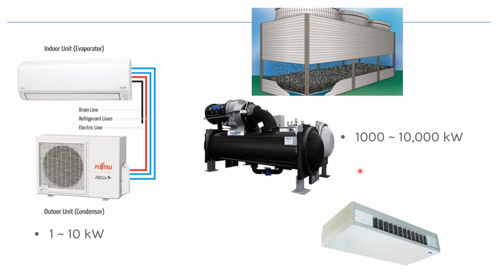And because the chiller cools down the cool water that you use to cool the indoor environment, it also needs some other part to take the heat away, for example, to reject it to the environment. So in this part, it needs another connection to the outdoor environment. Very commonly, we use cooling towers.